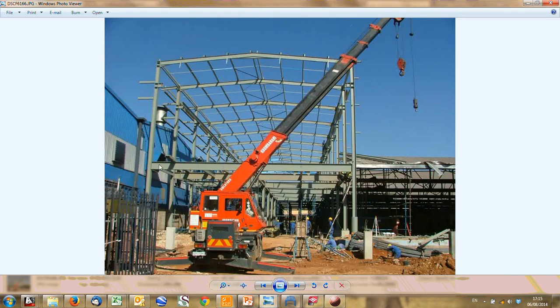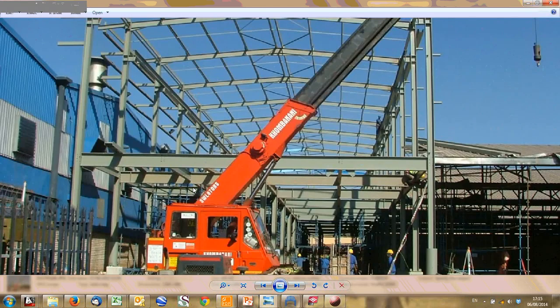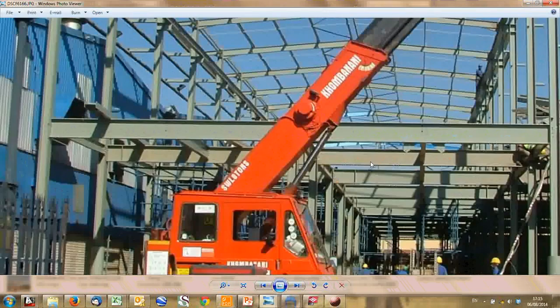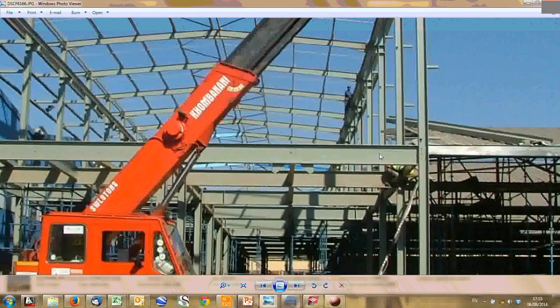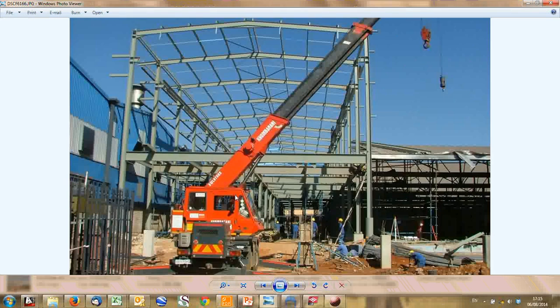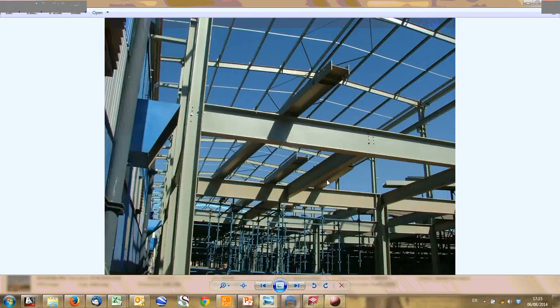This has got a big composite deck. This is steel beams with concrete on top, and then a sort of a portal frame. This obviously is a fixed connection up here, or it's a fixity from one to another. With the bottom, I'll show you just now, these are actually pinned beams. Because if you don't connect your flanges, you can't transfer moment or negligible moment from the beam to the column. So these become pinned connections around. And this structure, though, once the deck is cast, if you look through here, here we go. There's some pictures of the beams.